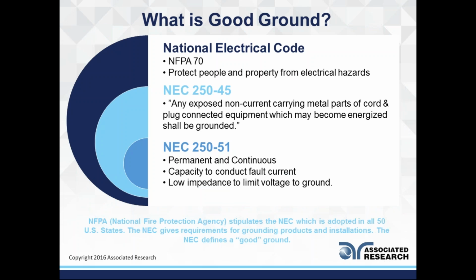So what is a good ground? There are ground standards called out in UL standards and NRTL type testing, and then there are also NEC codes that state it's to protect people and property from electrical hazards. NEC 250-45 states any exposed non-current carrying metal parts of a cord, meaning it's not designed to carry any current.